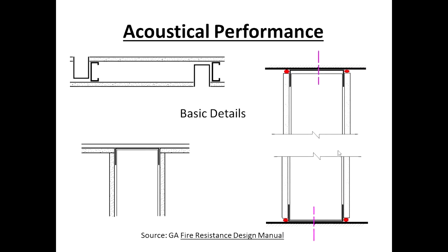I was taught early on, Mies van der Rohe said, God is in the details, and that is so true in acoustics. You could look at it as a corollary to that, which is the devil is in the details. If you look at this partition here, it's a section, there's your head and there's your base. If I take that partition and say it's a 50 STC partition and I punch a 1 square inch hole that goes all the way through, in other words, through the one board and through the other, that 50 STC wall will drop by 10 points.